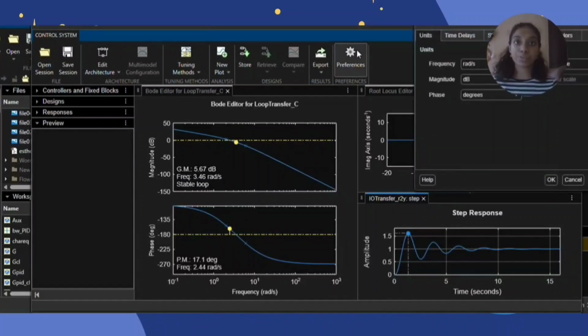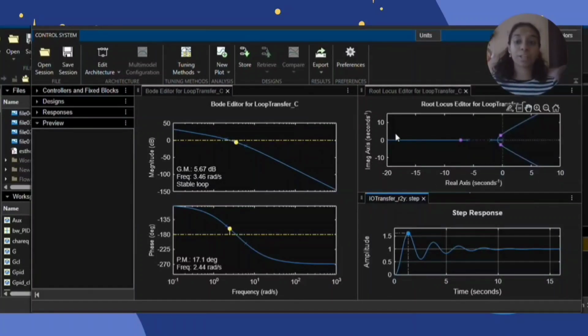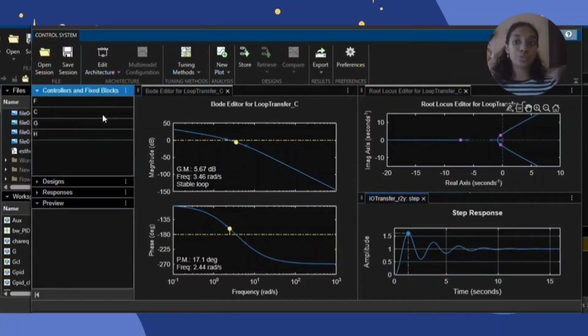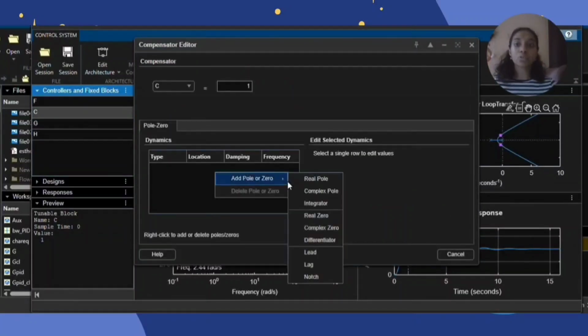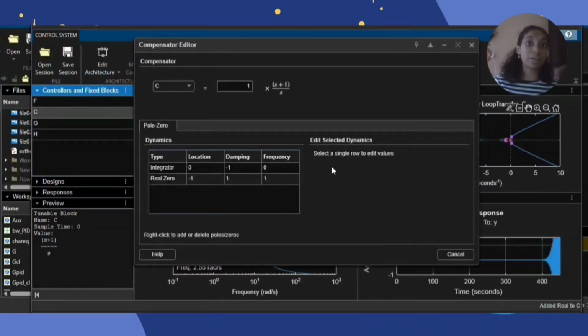So here we'll be adding an integrator and 2 real zeros, exactly like it was shown at our command window, the transfer function of the PID controller. So the value for real 0 is negative 2.0132 for both real zeros, and our gain value is 0.1987. So after adding this value, we will now check our overshoot, which remains at 55.4%.